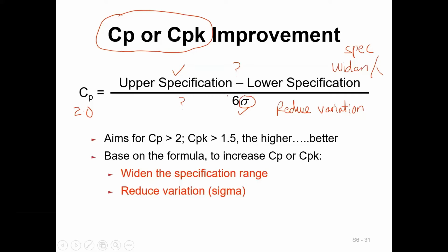Then the next thing I'm going to do is calculate what is the acceptable variation of the machines that allows me to produce the product within 6 sigma level. You get me? I've got the spec, I've got the CP, calculate the sigma, and that is the sigma that you should control. You try to reduce the sigma, the variation of the process, by studying the 4 M's until you reach the level that you calculated.